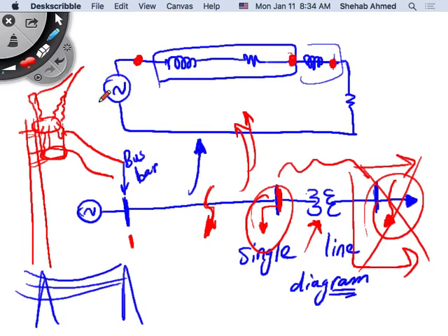Their job, these insulators, which we will study a little bit further down the road, is this: if this cable here has a voltage on it, and the housing of this transformer is connected to the ground potential, there's a big voltage difference between the two. If there's a big voltage difference between any two devices, do you want to bring them too close to each other? Why not? Why don't you want to bring two electrodes with very high voltage difference between them close to each other?